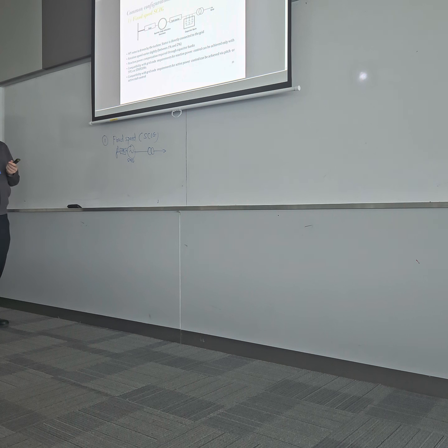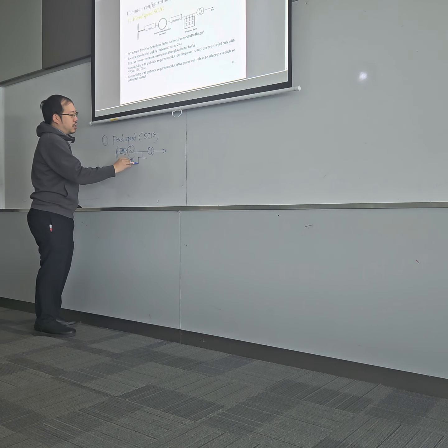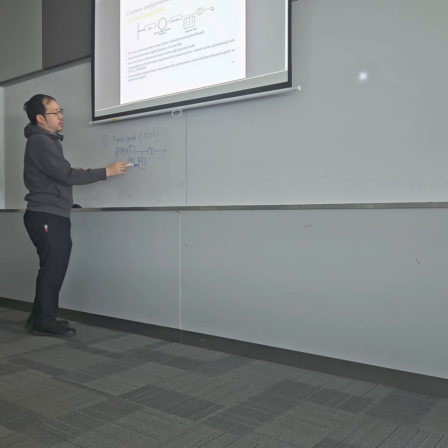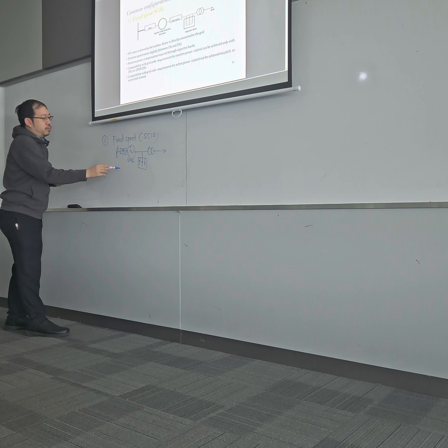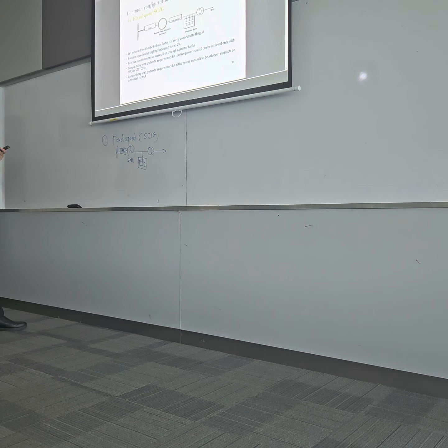The rotation speed only varies slightly between 1 to 2%, and in some cases you have reactive power compensation through the capacitor bank. So you will have compatibility with the grid code requirements for reactive power control, but this only can be achieved with the SVC or STATCOM.